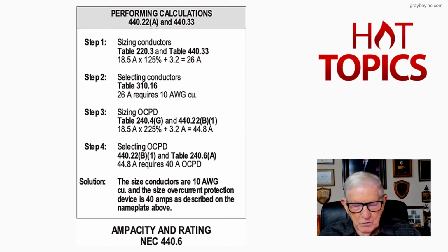The sum of the full load current rating of all other motors, and 25% of the largest compressor or motor full load current in the group. But we don't have a group now. That's why you have the parentheses for the S there, because we only have one compressor and one condenser motor.